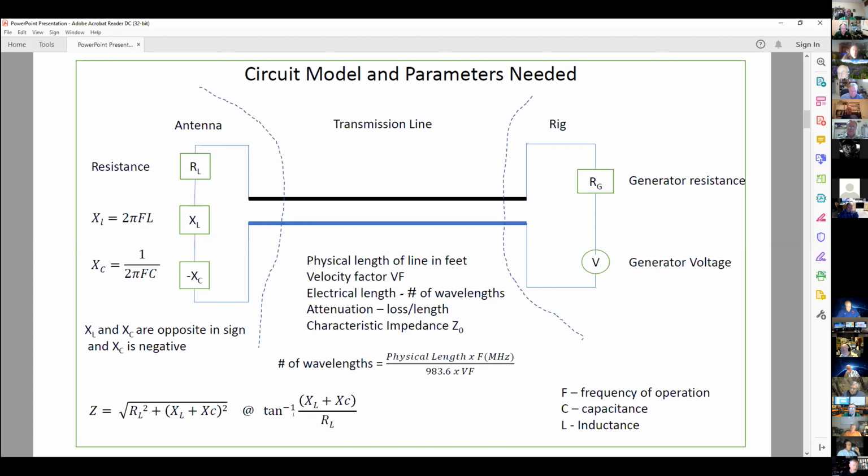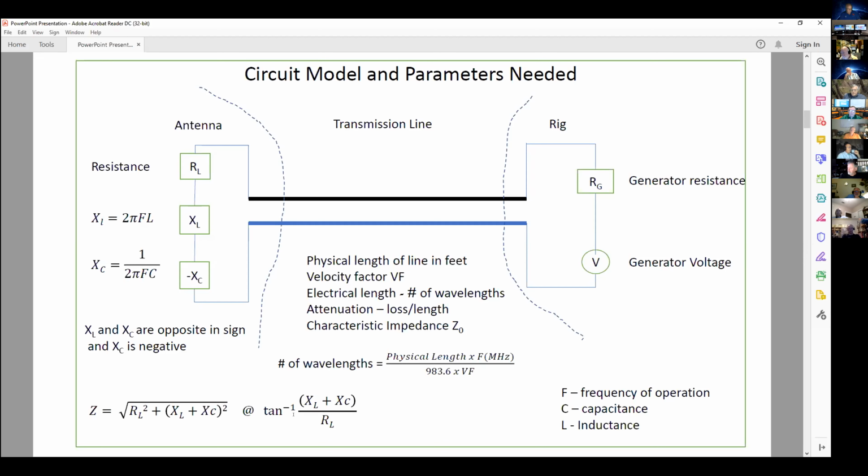So an impedance will have a number like 50 at 20 degrees, or 50 at 0 degrees, or 50 at 100 degrees, or 300 at 40 degrees, or something like that. And with that information about the angle, I can tell you how much is resistance and how much is reactive, and I can tell you whether that reactive part is inductive or capacitive.